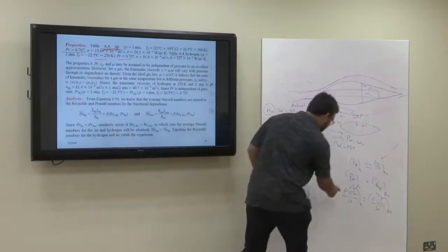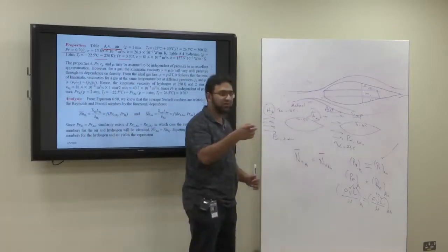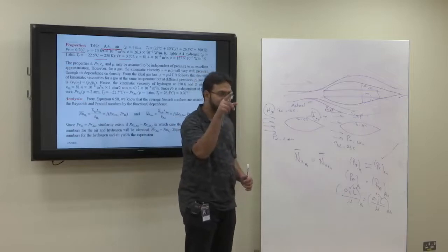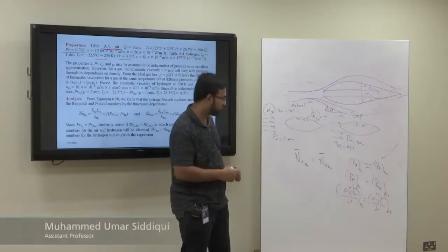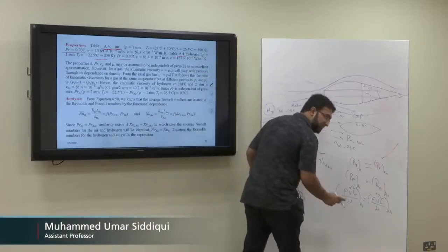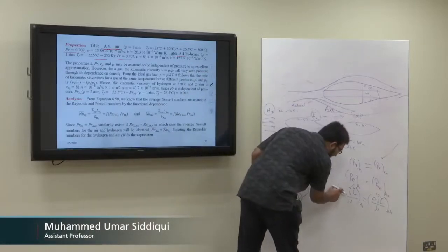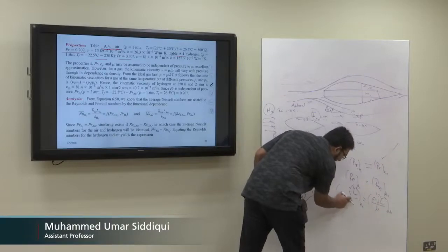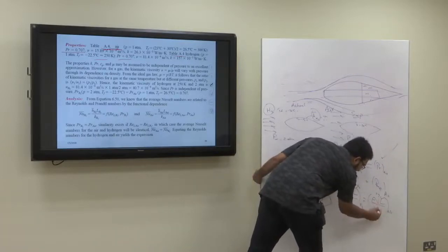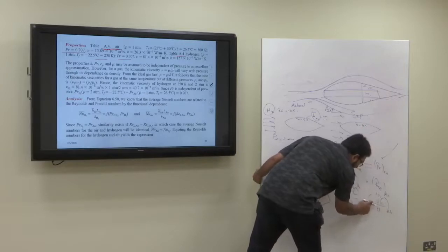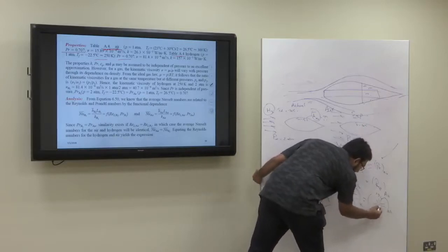Okay, just a minute. Here, if you find out in the properties, we are given kinematic viscosity. Dynamic viscosity is not given, right? So instead of writing VL upon mu, I can write VL upon nu. So now this term is there, and we need to find it.